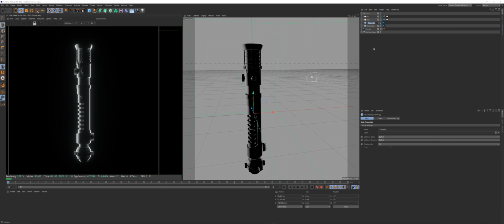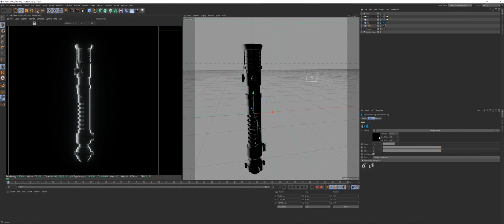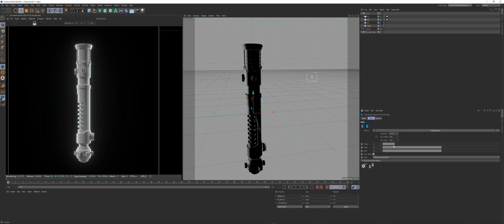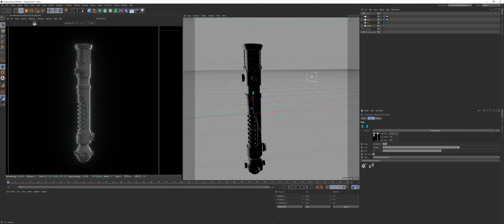You can call this one BG, and you can call this one HDRI, and then I'm going to put in a studio HDRI. You can use whatever one you want. I've got this rim light studio HDRI, and I'm not really going to have it doing too much work in the way it lights up the scene. I'm just going to keep it there for when we bring in reflections. So I'm going to keep it quite quiet for now. I may even change that if it doesn't give me the look I want.